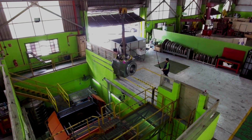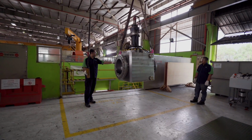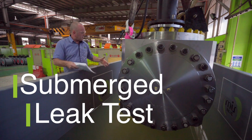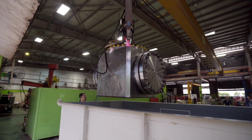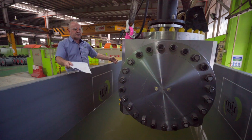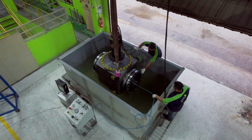After 4 days of testing on the bench, we are coming towards the end of this FAT. We are now standing at the submerged tank. So the tank is full of treated water. We have a corrosion inhibitor in the water. You can see now the valve is fitted with blind flanges. The valve will be lowered into the water tank and fully submerged.